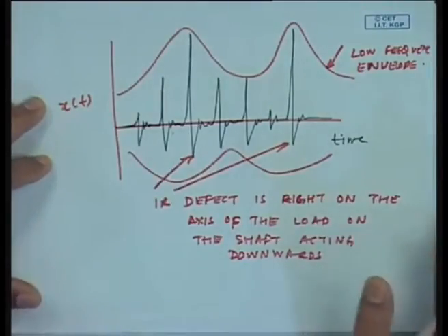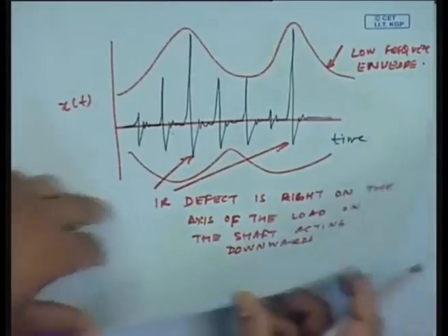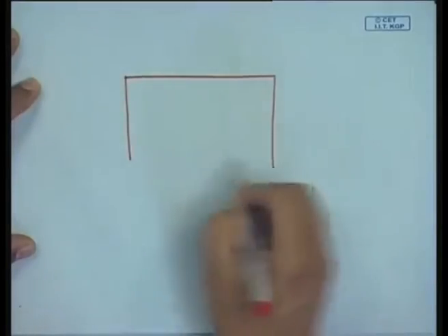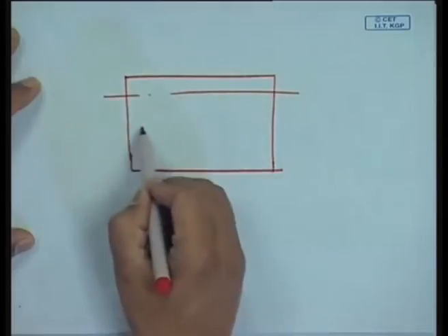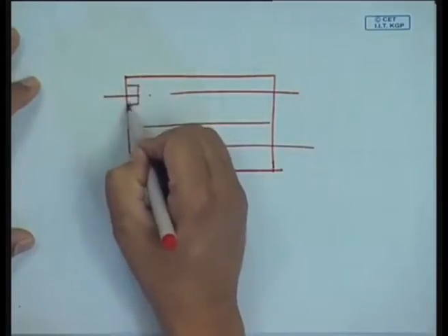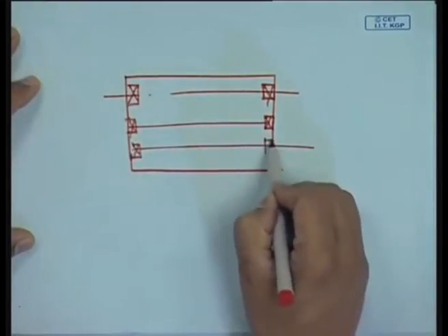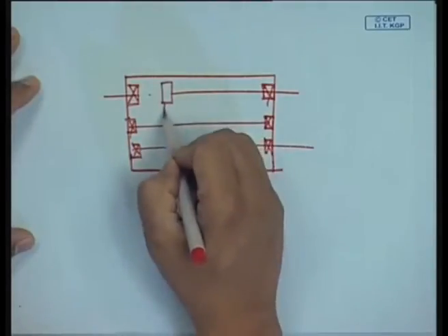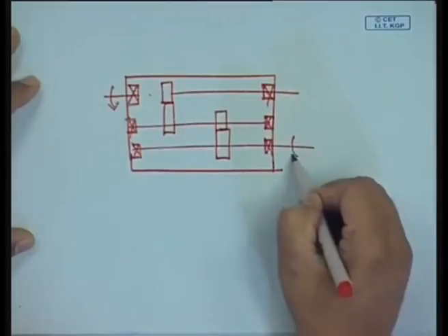Now, if I am talking about a gearbox with intermediate shafts, you can imagine there are about 6 to 7 bearings. If I put just one transducer on the machine, it is to measure the severity and magnitude of the vibration levels and what kind of contamination it may be having. Suppose this is my shaft, this is my gearbox. There are bearings here, bearings holding the intermediate shaft, and there could be gears. This is my input shaft, output shaft.